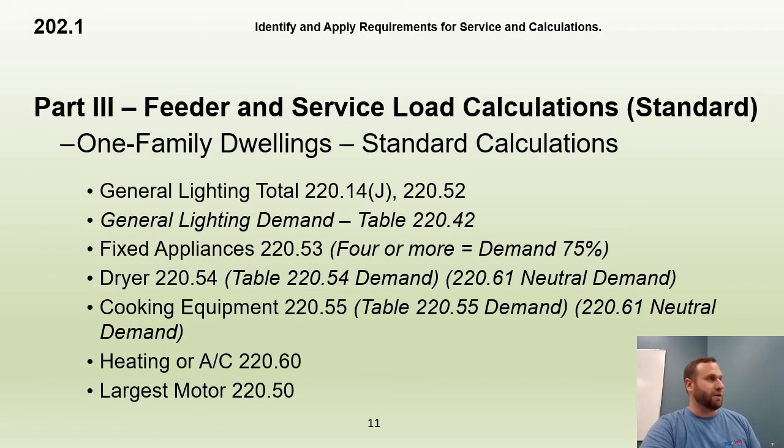A lot of their main power is found in the heating element, which has no neutral at all. Usually the neutral is only used for the small circuits within the range or in the dryer, like your light bulb and your fan, all the bells and the whistles that come with a dryer or an electric range. Maybe even the Wi-Fi adapter that helps alert your cell phone that your meal is done cooking or something like that. I don't know. But that gives us permission to not include the entire range on the neutral. That's step 1, 2, 3, 4.